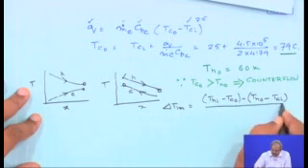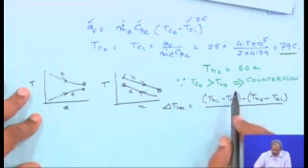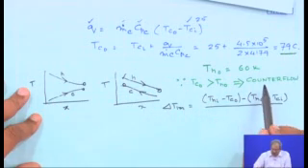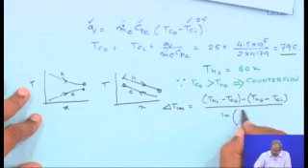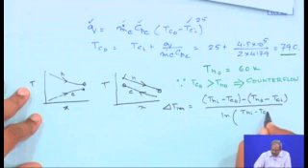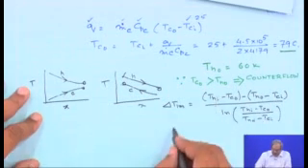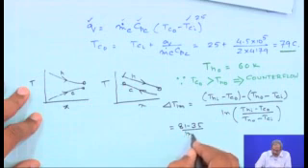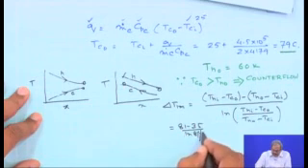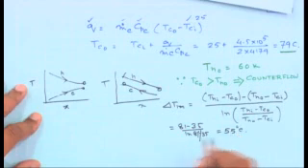This would obviously be different if it's a parallel flow situation. That's why it's important to know whether it's counter flow or parallel flow, and this is simply going to be the ratio of these two. Once you put in the values, this is going to be 81 minus 35 by ln 81 by 35, which is 55 degree centigrade.